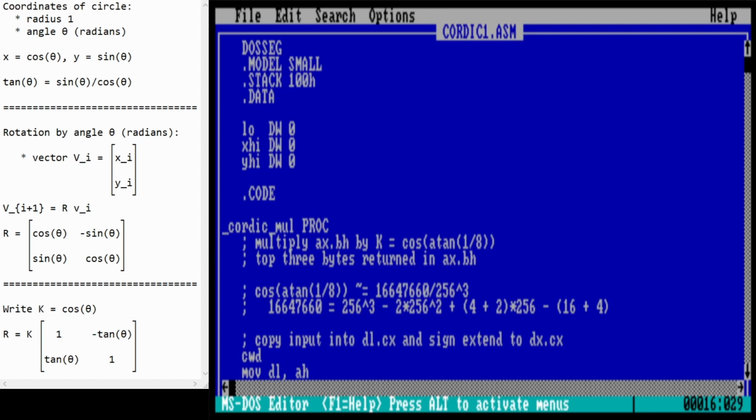So the problem with this value is that there are a hell of a lot of ones in its binary representation. And normally when you do multiplication in binary, what you do is you take the input and you shift it left lots of times, and you just move along through the bits of the multiplicand, and every time you get a 1 in the multiplicand, you add the shifted value so far to the result. But if there's lots of 1s in this multiplicand, that's going to be a very, very expensive operation.